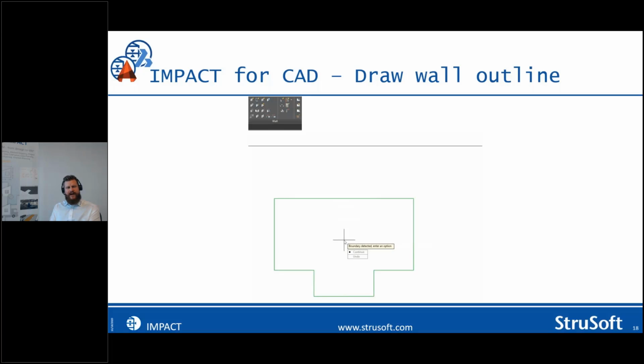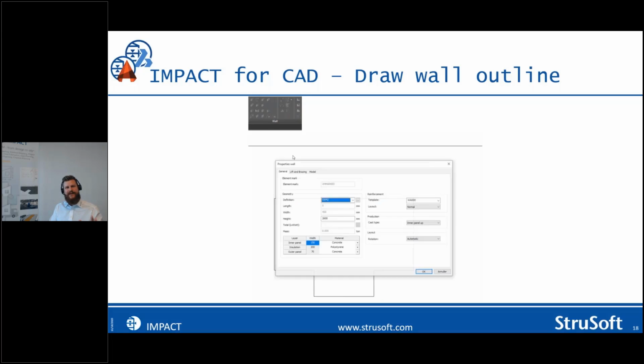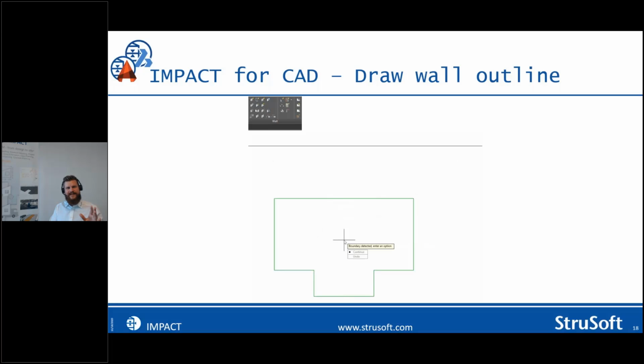So this draw wall outline is a tool to make this early stage of modeling much faster than what you're doing today, where you will draw the wall around and then you will need to do maybe a joint or something to make a corner. In this case here, how the corners are oriented is not the most important thing, because this is meant to make this modeling phase really fast, and to have some model that you can do some sort of takeoff on really fast.